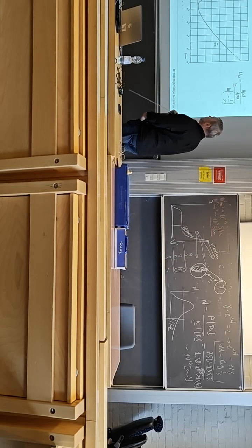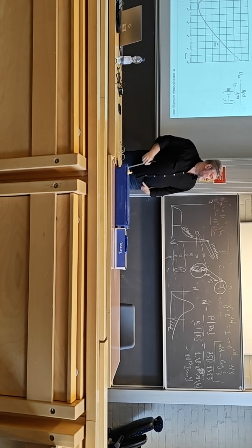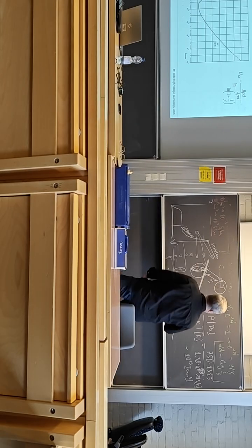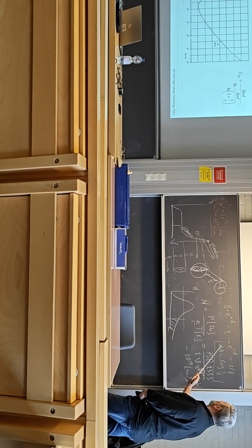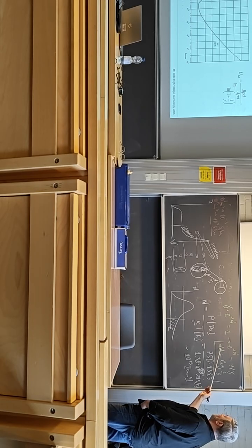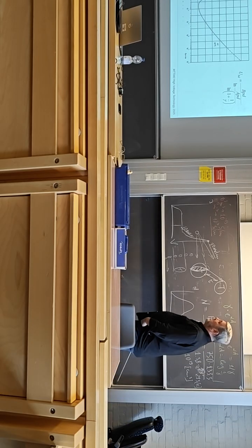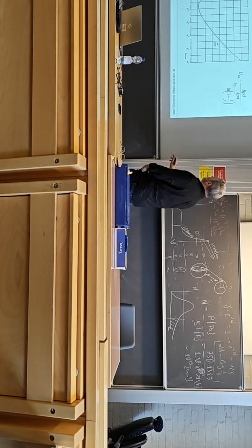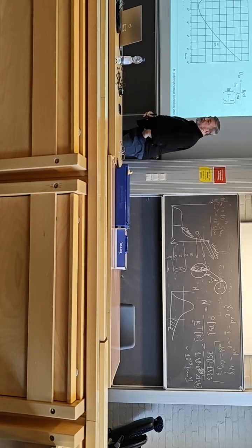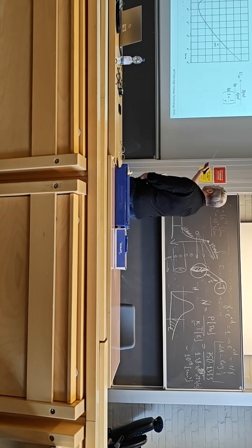It's not rocket science, it's just a few lines of formulas, because you have to start with this condition, and then express alpha with some given empirical expression. Then, assuming that breakdown voltage is the breakdown field multiplied with the distance, you just rearrange the terms and arrive at this.